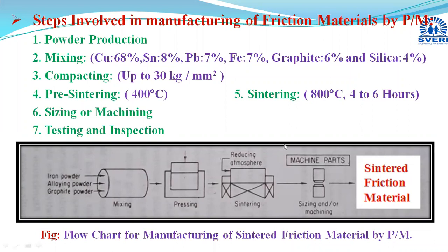It is tested and inspected for its shape, size, and different properties or characteristics, like microstructure, composition, tensile strength, compressive strength, hardness, and whether any porosity is there.